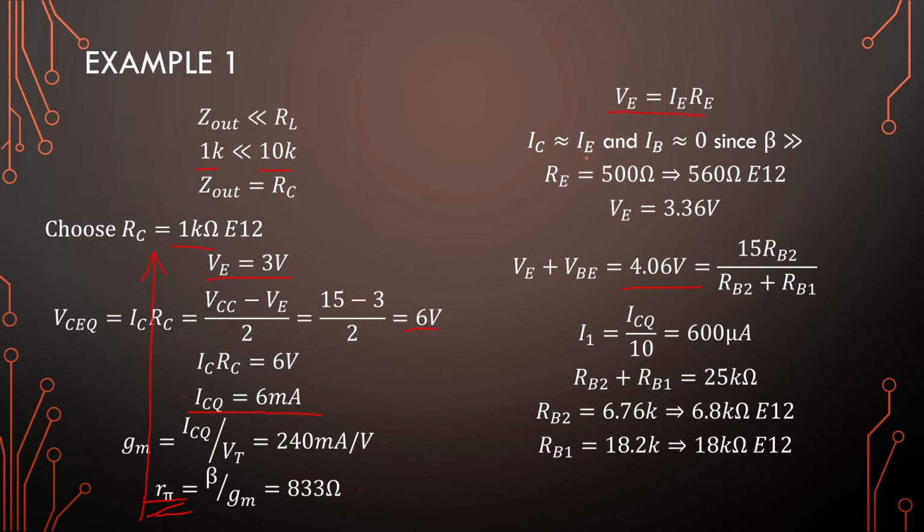So in practice, you would typically design this, plug in the resistors, and do the simulation, and then knowing what each component's function is, you can tweak your amplifier afterwards. But knowing beforehand what the function of each component is will also help you to make the correct choice. Should this be 470 ohms or should it be 560 ohms?